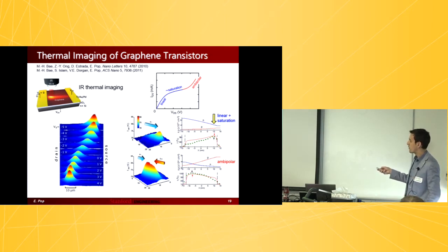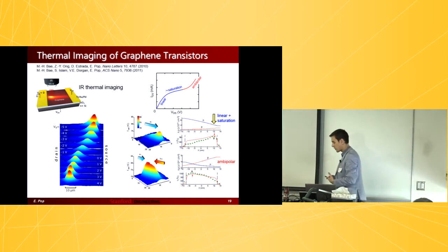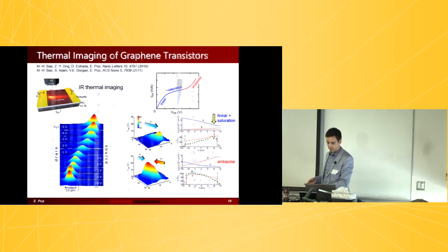And so if they form in an X, the electrons and holes, there's going to be a point of minimum carrier density that's actually in the middle of the channel. And that's going to be the point of the highest electric field, hottest region, and so on. And that's when the hotspot moves to the middle of the channel. And so we see this. It's a nice way to thermally observe the carrier densities inside the channel. That's essentially what is happening over here.